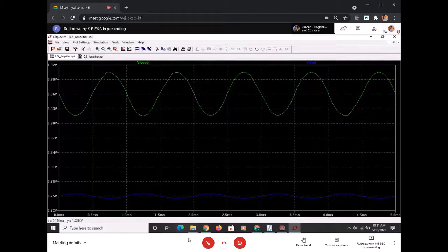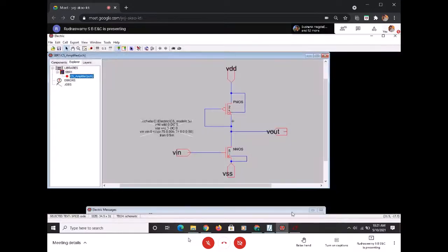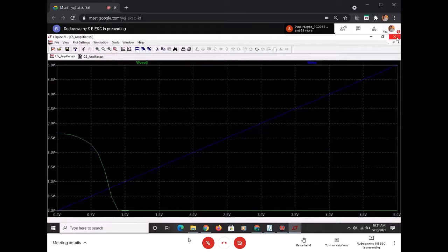Keep changing the parameters mu n and mu p, and also the operating point. Okay, I've used 0.75. It was 0.766. You can even keep 0.766 and see. So two parameters you can vary. Give the operating point whatever you have got, and vary mu n with respect to mu p, 2 or 2.5 or 3 or 2.2, whatever. Okay, and just plot. So that's the design aspect.